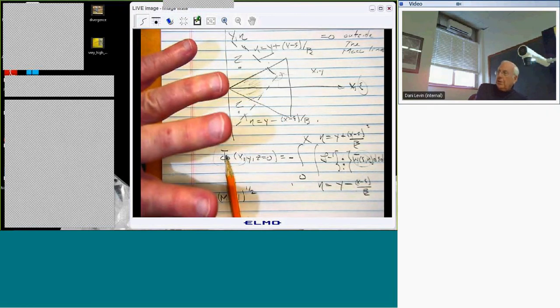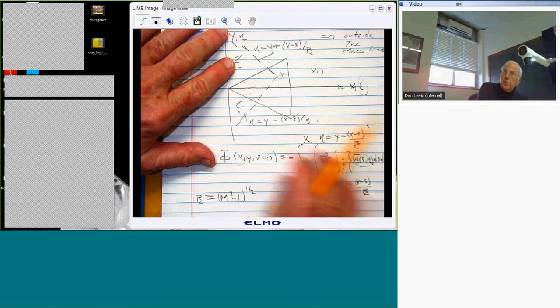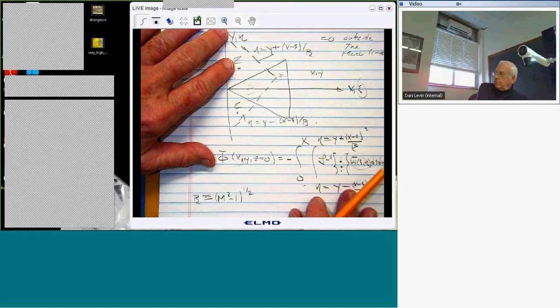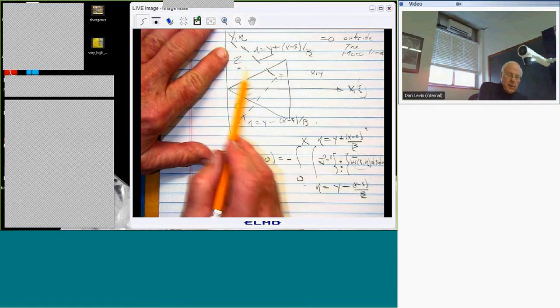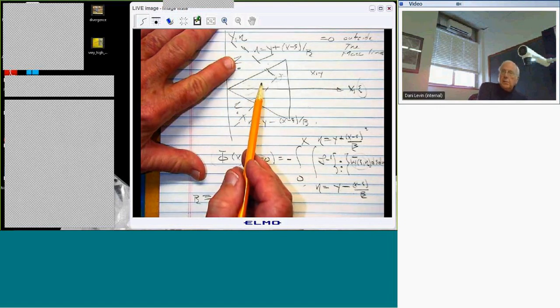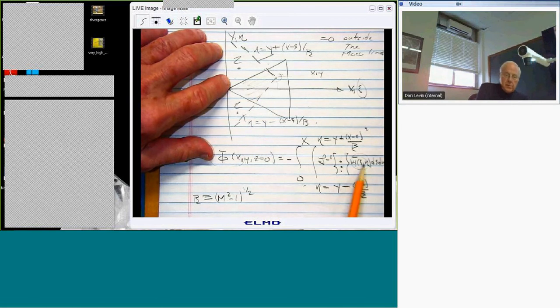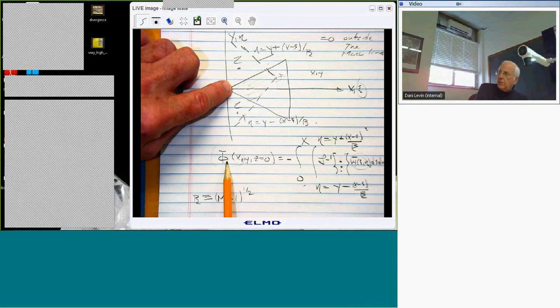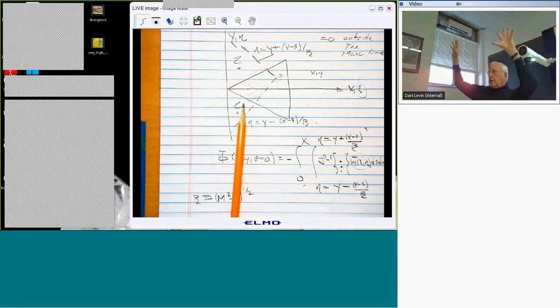I'm in good shape. And so what I basically would do is I would write a computer code. Probably not ask you to do this. They're commercially available. I divide this area up into boxes, right? And in each box, I assume either this or this is a constant. Actually, off the wing, I assume it's only constant at 0. And then I set up a matrix equation, right? And I rearrange things so all the knowns are on one side and all the unknowns are on the other side, and I do a matrix inversion, and I'm done.